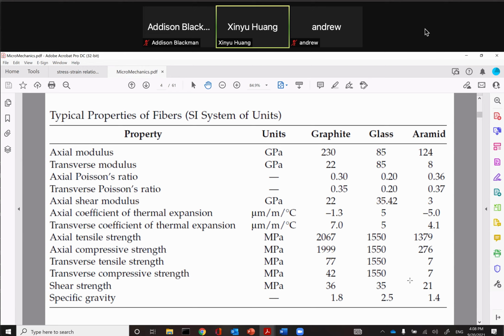The fibers are aligned in the axial direction, the way they parallelize and pull together, they align the strong bond in the axial direction. What if you pull the fiber in the transverse direction, what kind of bond are you dealing with? It's a secondary bond, the bond between the graphene sheets. That's a much weaker bond. That bond is not strong. So basically, this is the fundamental reason why that direction is much less stiff than the other direction. Now you look at the glass; it's the same. The glass is an isotropic material.